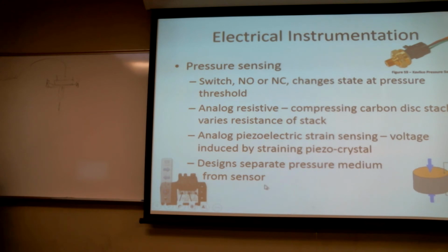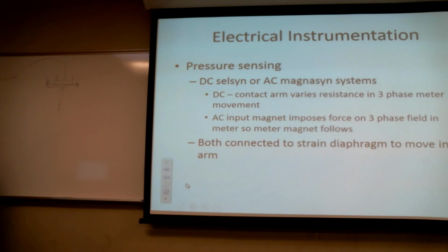Another one that's a piezo sensor, this one right here, is actually a standard automotive MAP sensor being used to measure manifold absolute pressure. Feed it 5 volts and ground, and it feeds you electronic data, a 0 to 5 volt scale for manifold absolute pressure. You then take that voltage and feed it into your computer, and then it'll do something.